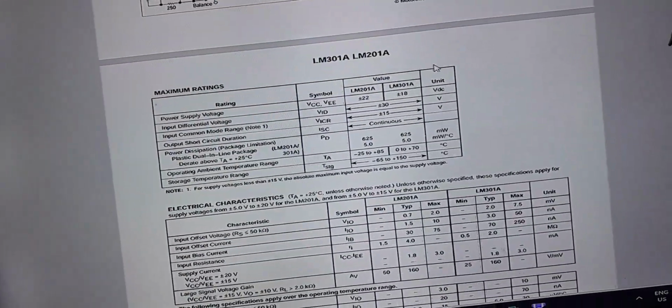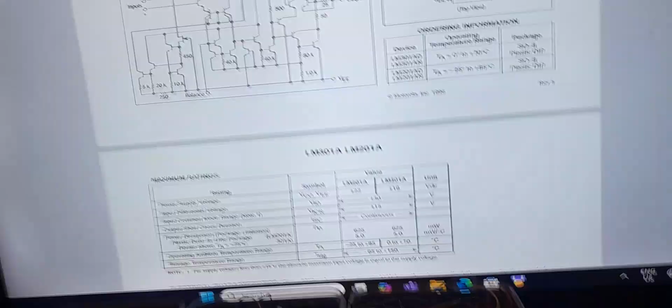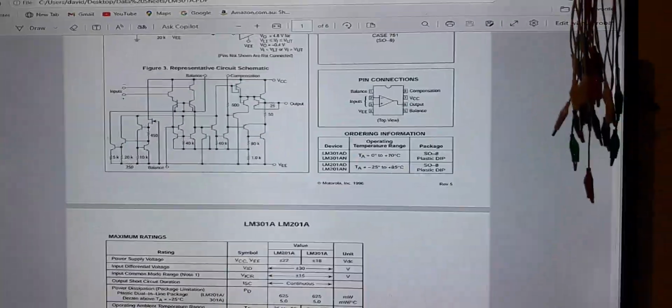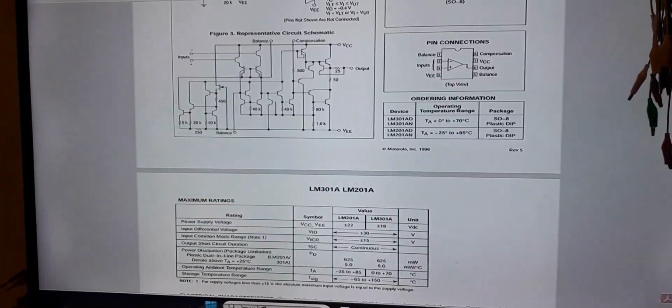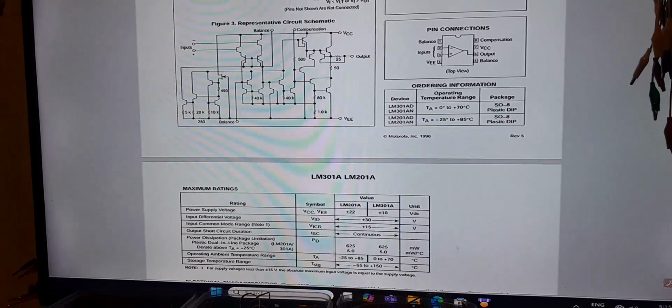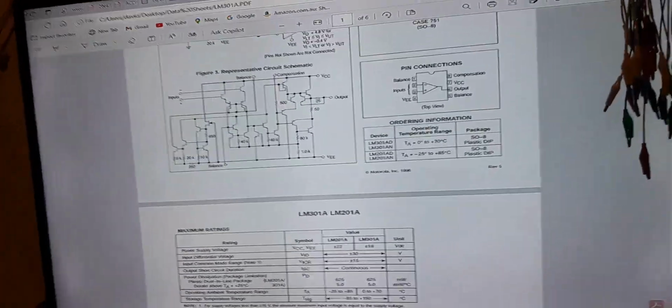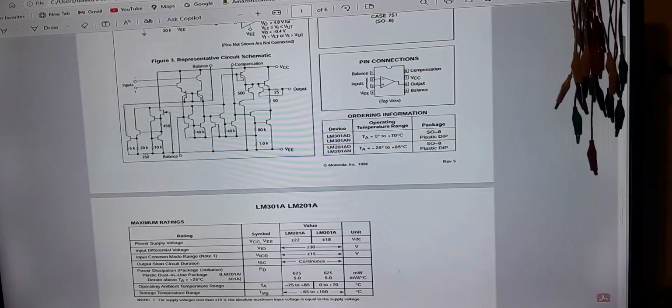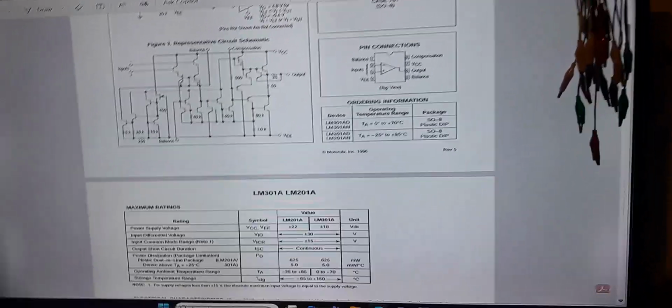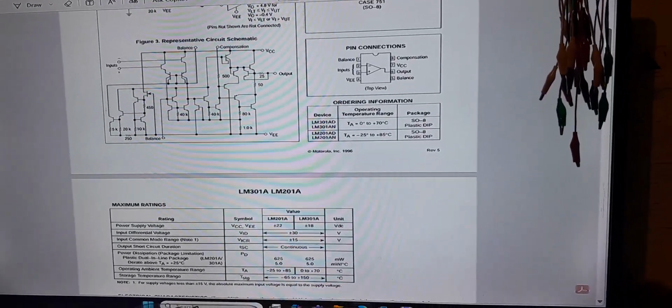Alright, well, I'm going to go compare a few different data sheets because I have got tons of components. I've probably got like 30 different types of op amps in here. I'm going to go compare data sheets and work out what op amp I'm going to use. It's not going to be JFET input. I got a funny feeling the main problem I've actually got here more than the topology of the op amp is the JFET inputs themselves.